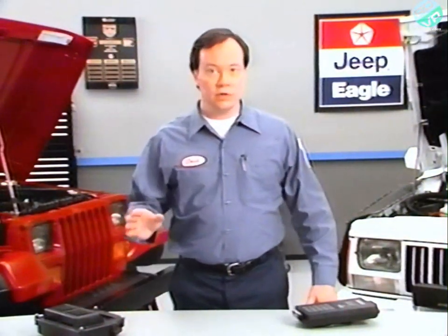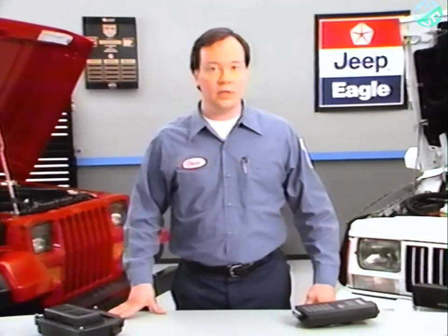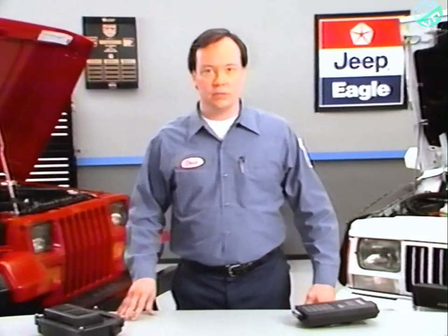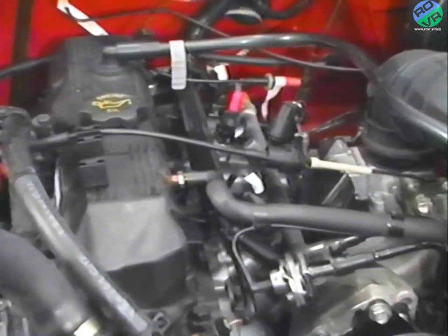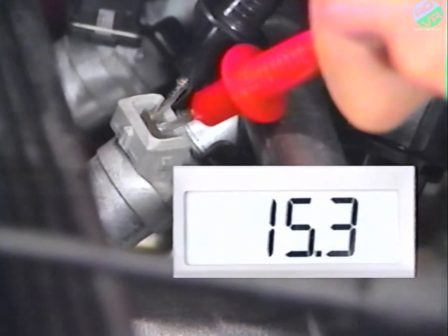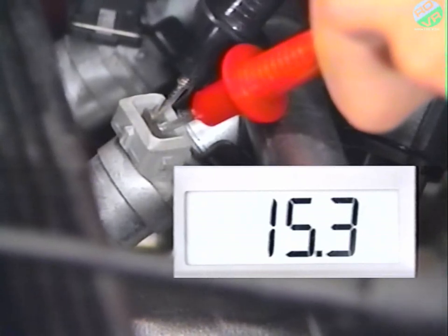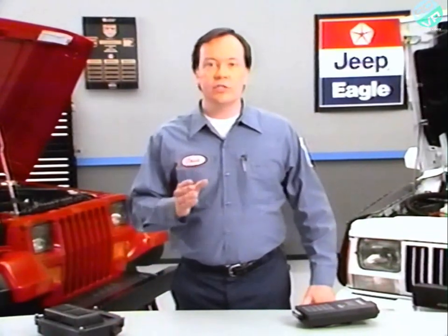The 1991 service manual contains a procedure for diagnosing fuel injector problems in vehicles with a drivability problem. We'll use part of this diagnostic procedure to diagnose the problem. The first step is to start the vehicle, and with the engine running, disconnect and connect the electrical connectors on the fuel injectors one at a time to determine which cylinder is not firing. Injector resistance is tested by removing the connector and connecting an ohm meter across the injector terminals. The resistance should be approximately 14.5 ohms. If it isn't, the injector is faulty and should be replaced. In our case, the resistance is correct.